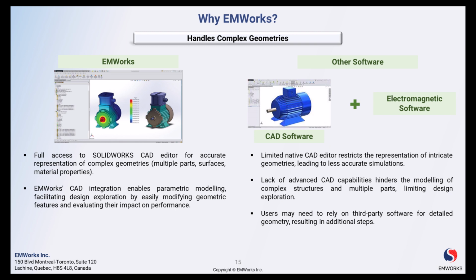Furthermore, EMWorks CAD-embedded tools like EMS 3D can handle the most complex geometries with ease. Users get full access to SolidWorks' advanced modeling capabilities. Intricate components, curved surfaces, and small features are represented accurately, which is critical for real-world electromagnetic performance. Detailed CAD modeling coupled with automatic meshing enables high-fidelity virtual prototyping. Tools lacking native CAD integration often struggle with importing and meshing complex geometry from external CAD packages. EMWorks overcomes these limitations through its direct CAD access.